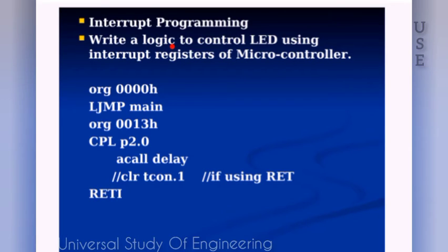And the 6th practical is the temperature sensor. What are we going to do in this temperature sensor? LM35 is the temperature sensor, which sends the temperature as an analog quantity. We are going to convert that into digital first, give that information to the microcontroller, and then from that microcontroller we are going to display it through an LCD.